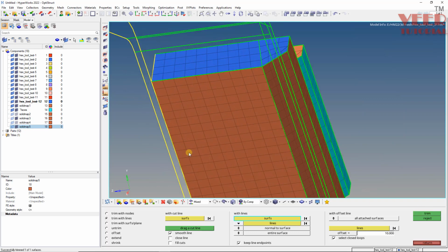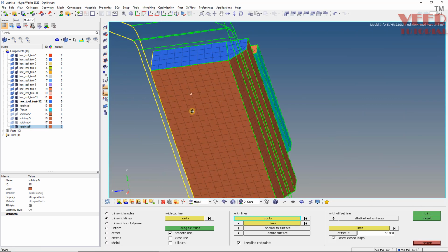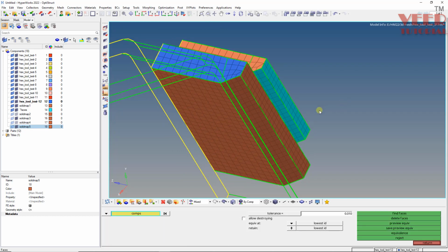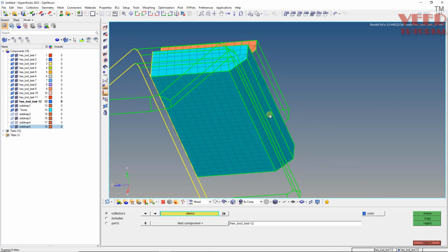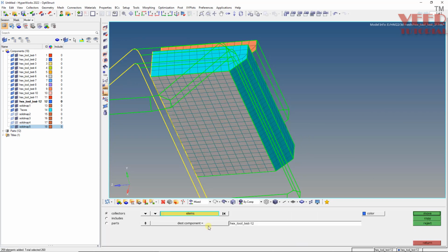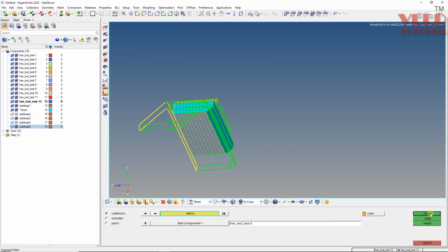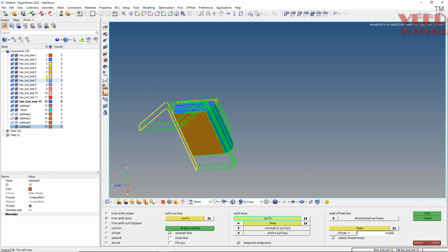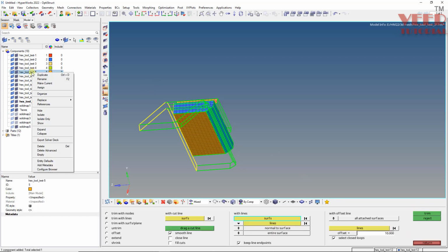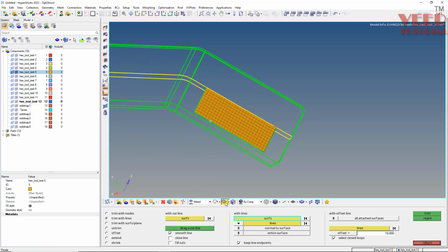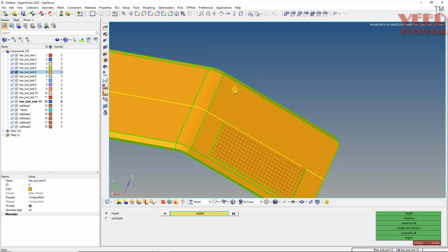Okay, now trim. After that we also have to project the mesh. So first extract the faces, then select this and find faces. Okay, so Shift plus F11, then select this element by face, then destination will be this yellow one. This is number 5, move. Okay, so this number 5 is our yellow one plate. Right click, isolate only, and solid view, I will go to mask and mask this right one.